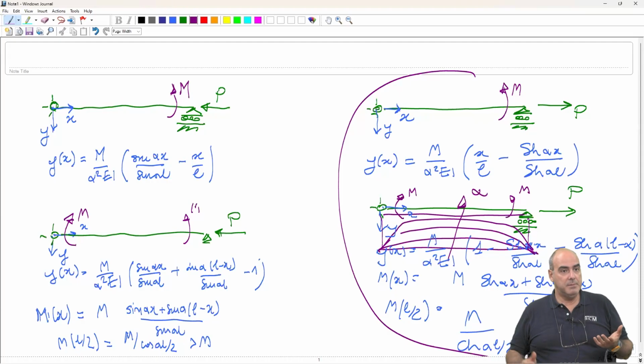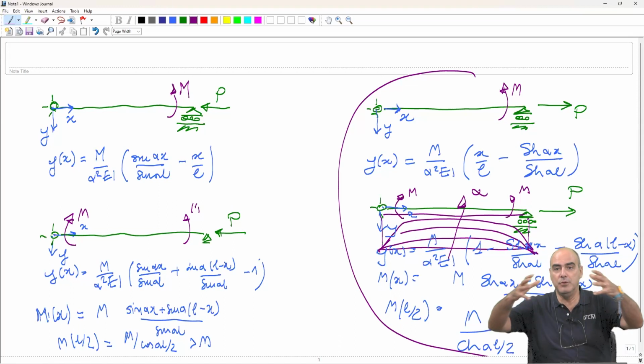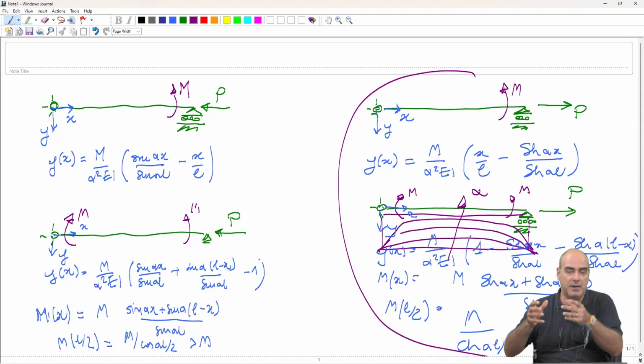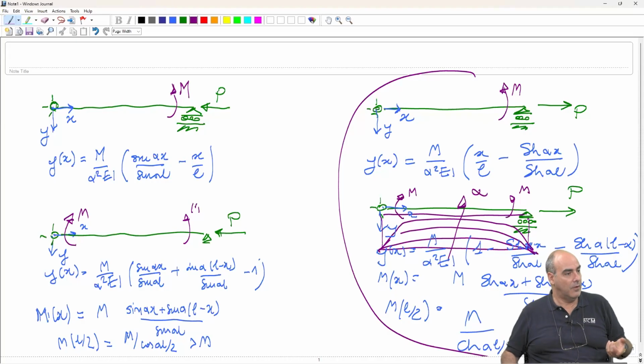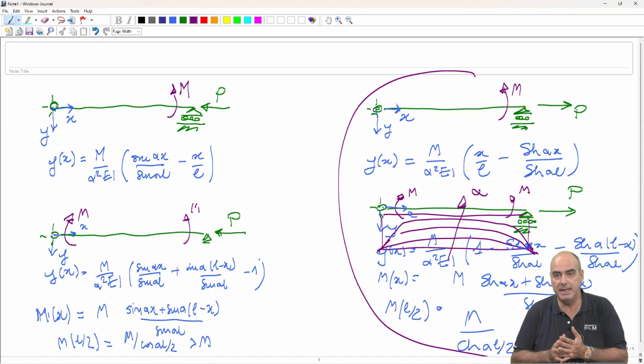Okay, a membrane is like a rope, like a thread. It cannot resist gravity loads because the membrane has no flexural stiffness. But if you use it to cover a space, you have to resist, well, not the self-weight because they are very light, but you have to resist snow load, in case. And how do you do that? Because you apply a tensile force and you confer to the elements, to a membrane element or to a thread element, the capacity to resist gravity loads.